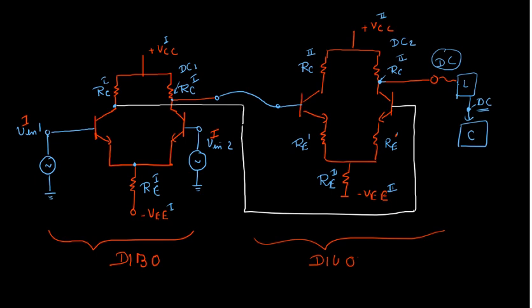Why did this happen? Because of the DC component present here, the operating point will set some operating point, then further we have VCC, right? So it will further shift our DC level. So I hope this makes sense now. Why do we need a level translator?